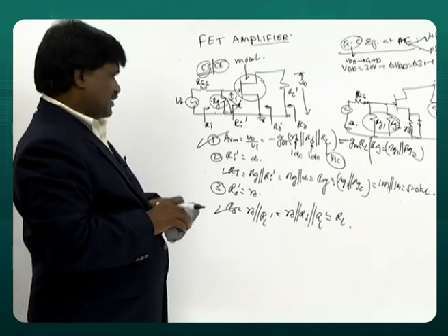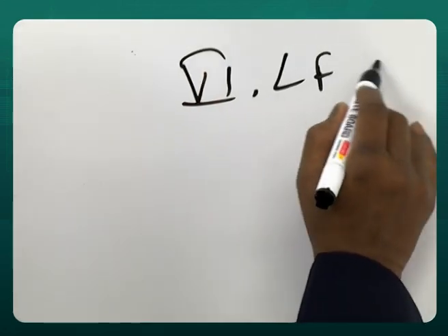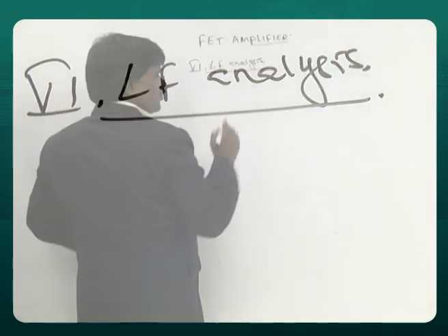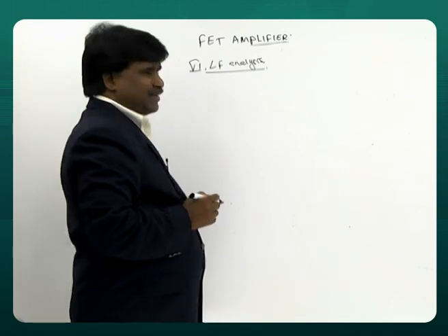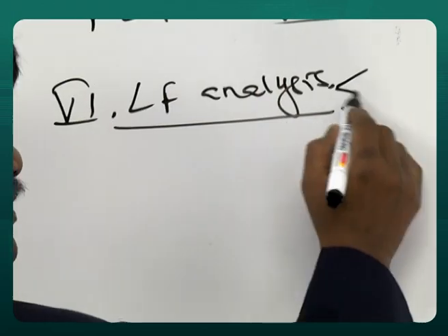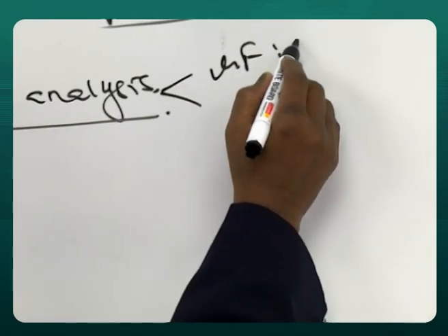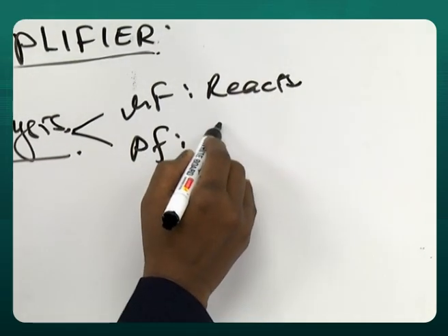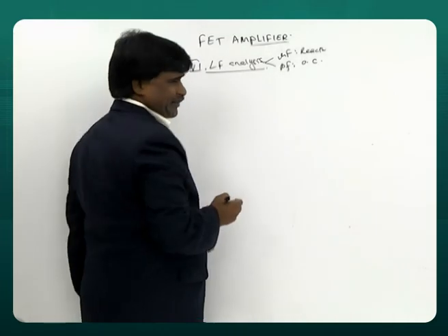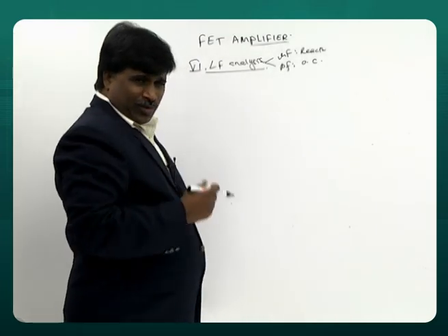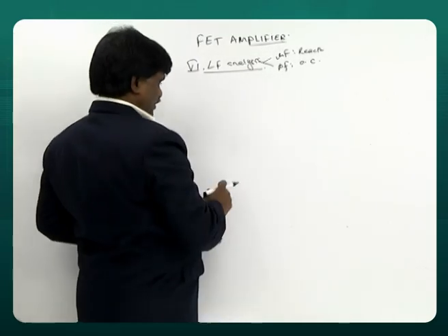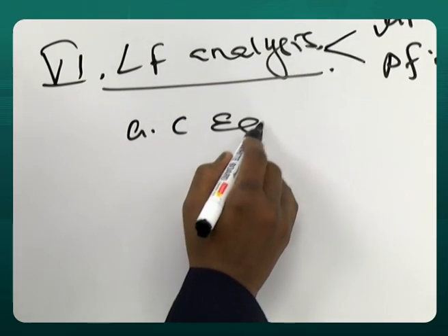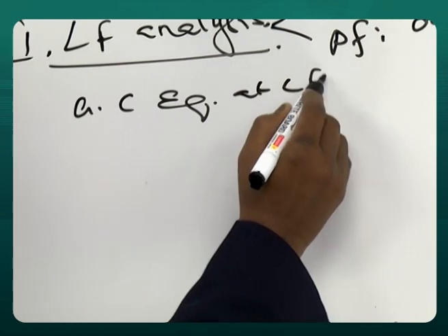So that's my fifth idea to talk, mid-frequency analysis. Sixth one is low-frequency analysis. What do you mean by low frequency? Low frequency means microfarad reacts, picofarad open. Now look at your circuit which I have given in the previous one. I will draw the AC equivalent at low frequency.